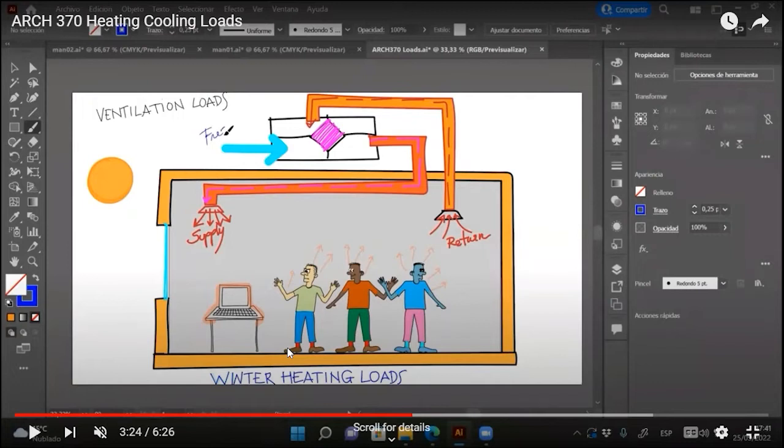If we have a heat recovery, we lose less energy, but in those exercises that we are doing, we are not having a heat recovery. We are considering that we have the fresh air, and then we heat up that fresh air up to the supply temperature, the comfort temperature. Next week, we will learn how to calculate the energy that we save with heat recoveries.